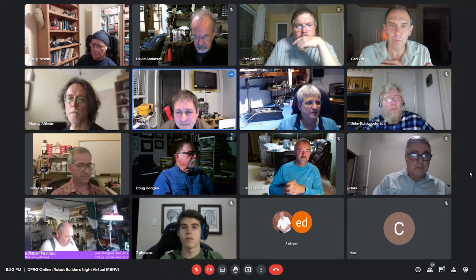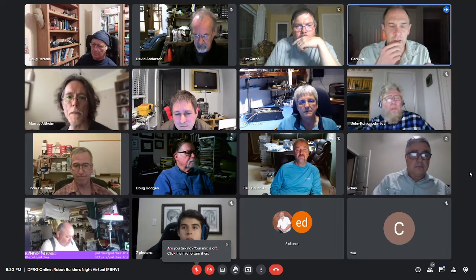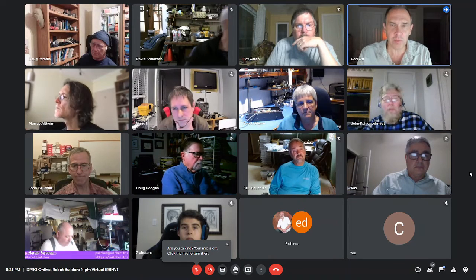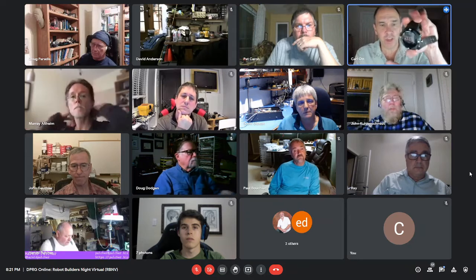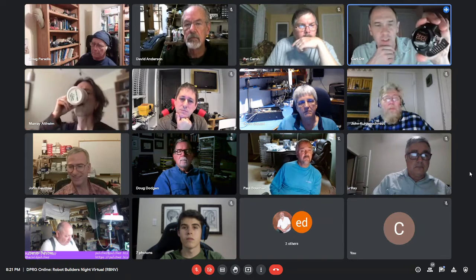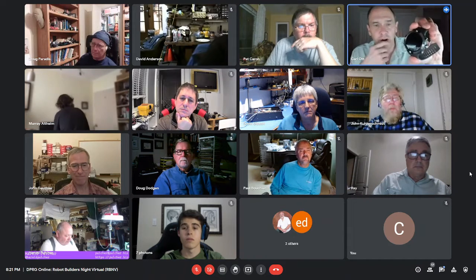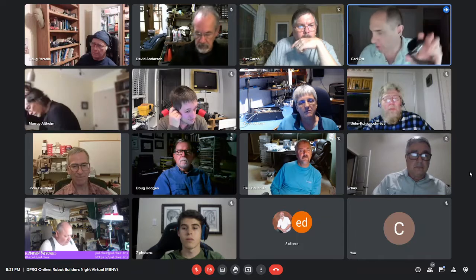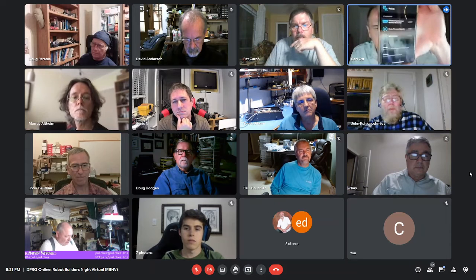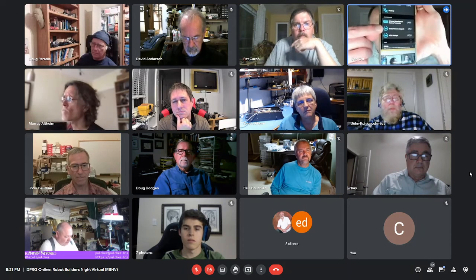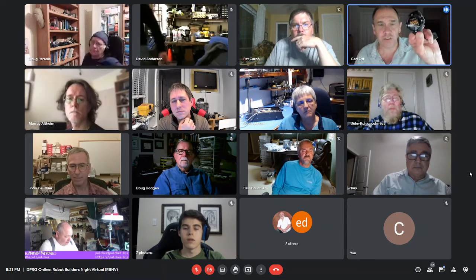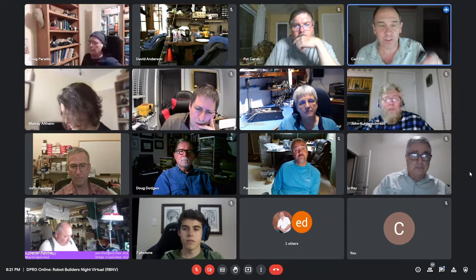No. See, you mentioned DFU, and I find that interesting because, as I've mentioned, I'm playing around with Espruino, and those are based on the Nordic chipsets. So this, for example, is a JavaScript powered watch that runs on an nRF52 series chip. And whenever I update its firmware, I do it through the nRF Toolkit on my phone. And as you can see, it has this DFU mode. So I don't have to use any pins or USB or anything. I click this button, I select the firmware image, it pushes it over Bluetooth, and it flashes the chipset. And they call it DFU.